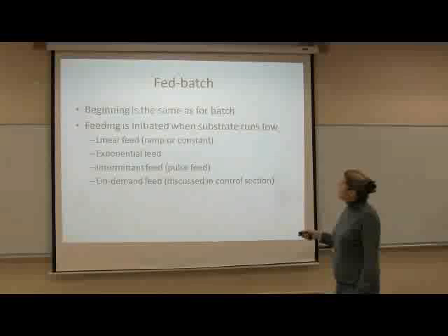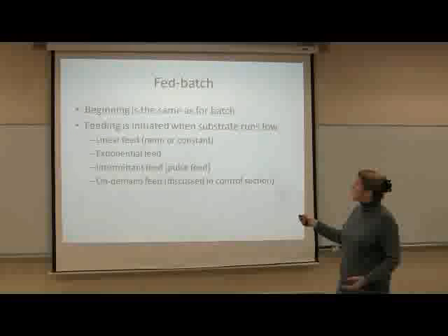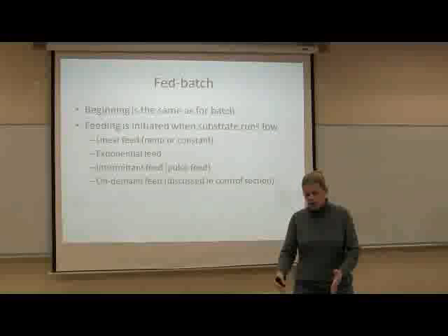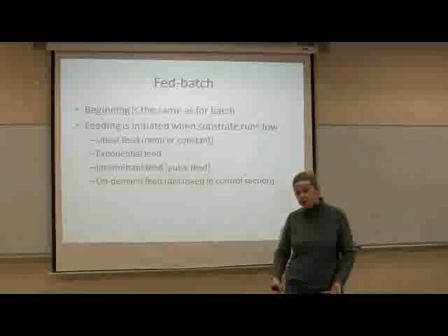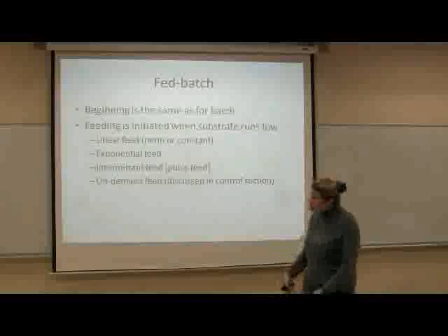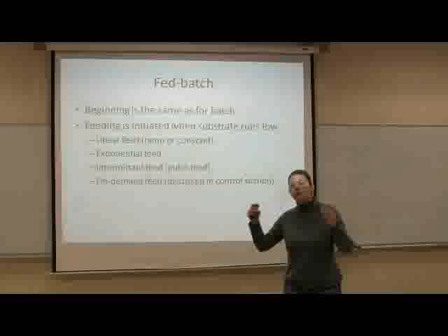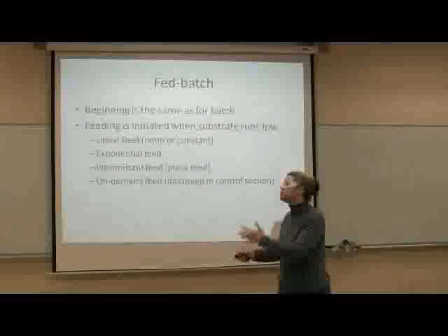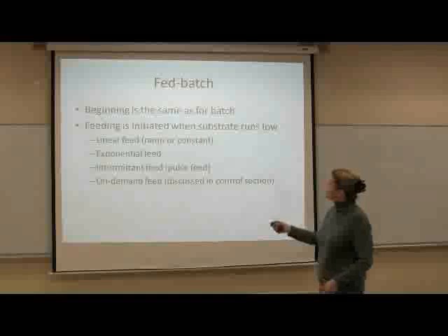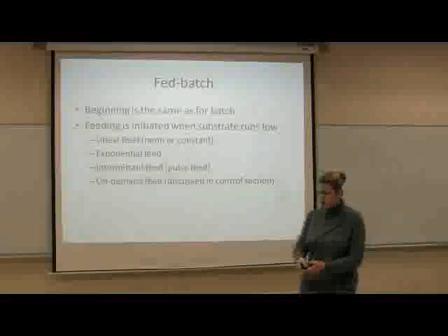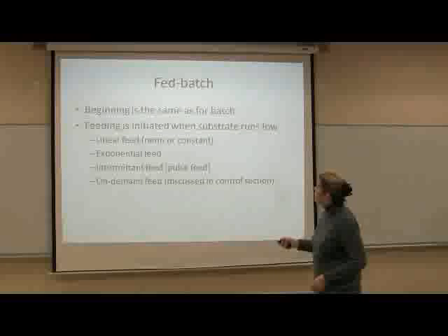So our process is going to be fed batch. It starts out the same as a batch process. Put the media in, put the bugs in, it grows. We're just controlling the pH and the temperature and the oxygen, and then when the substrate is all gone, we start feeding. And that's why it's called fed batch. So the only thing we're going to add is some substrate into the process, and we're going to feed that until the tank fills up. So that's what we're going to do.